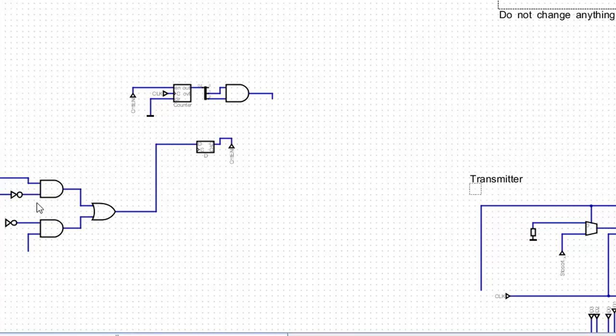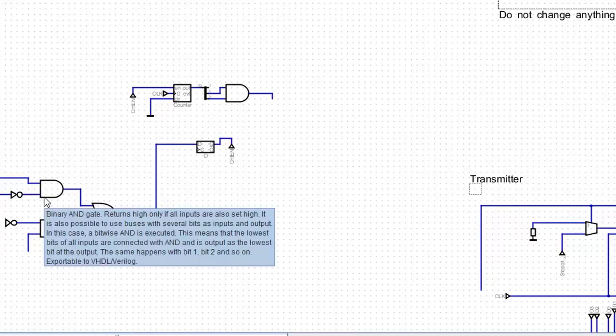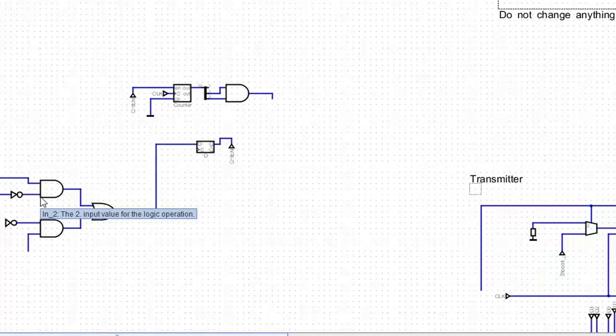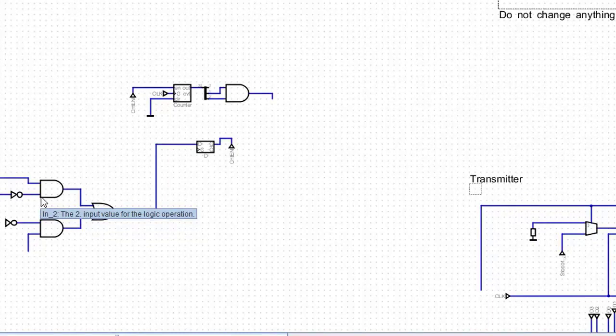Somewhere in your truth table, what is that thing that's NOTed? I don't know how you did your state machine, but basically the inputs into your next state logic are start TX, counter max reached, and present state. And that present state you've currently connected and called output enable. So maybe just zoom into the output of your flip-flop.